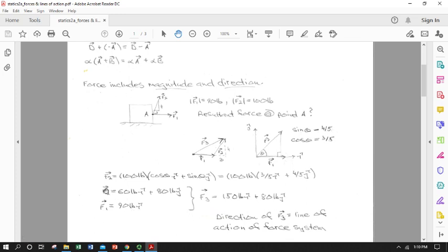So if I add two vectors, I'm going to add by direction. I add x's to x's, y's to y's, z's to z's. So i hats get added to i hats, j hats get added to j hats, and if I had a z-axis in 3D, it would be the k hat unit vector. So my vector sum, I'll just call it F3, is going to be 60 pounds in the x plus 90 pounds in the x plus 80 pounds in the y. So I have 150 pounds pulling in the x direction, horizontal, and I have 80 pounds pulling in the vertical direction.